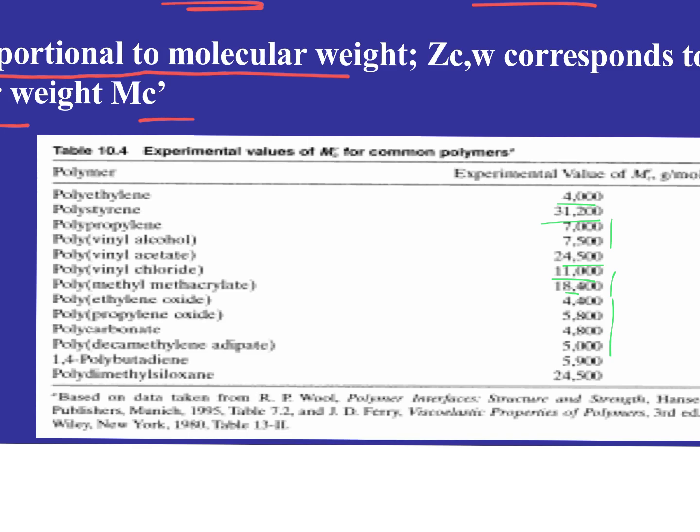However, they are moldable. And so for making something that's small and cheap, and we make a whole bunch of them, we're not going to expect these to bear a whole lot of load or be all that resistant to creep, but we don't care. If it's a kid's toy, so what? If it's a piece of the pen you're using, so what? It doesn't have to withstand a lot of stress, but it can be molded that way relatively cheaply because the molecular weights are lower.